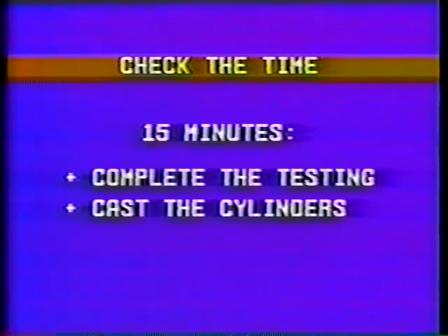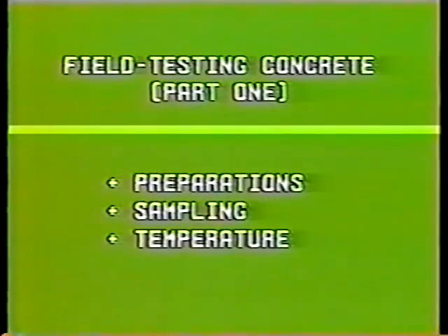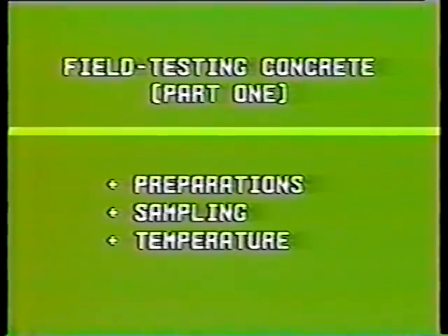One last point in sampling: check the time. You have 15 minutes to run the testing and cast the cylinders, if they're going to be made from this load. And that covers sampling. Now, temperature.